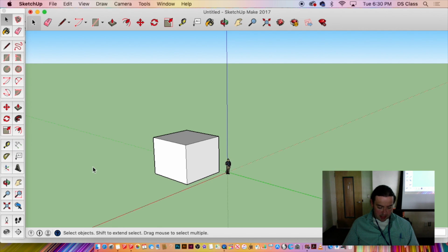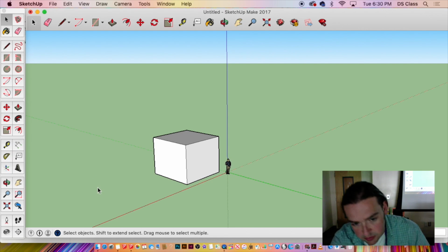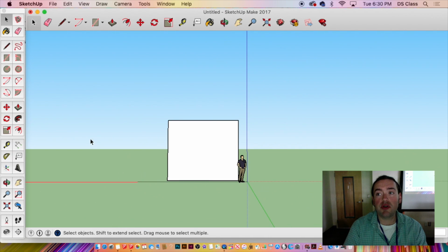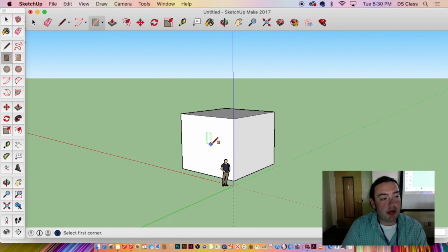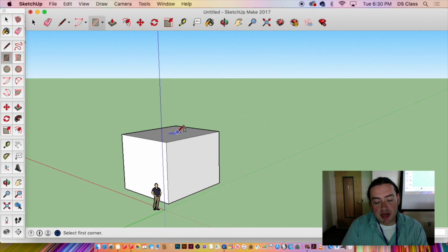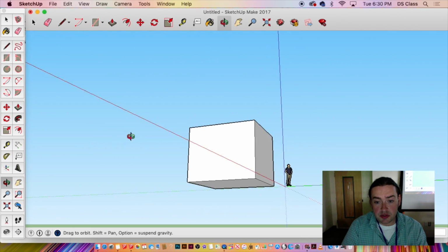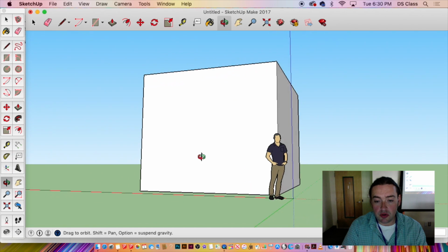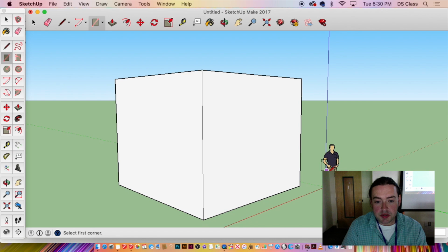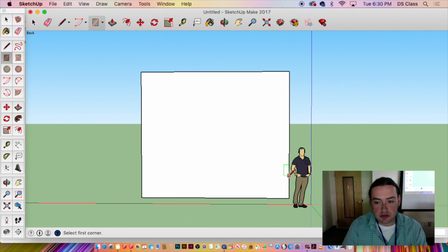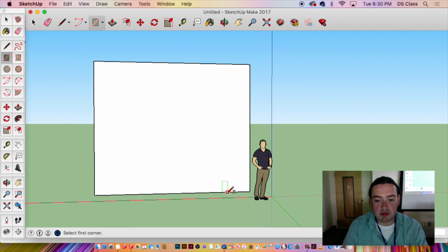So we got navigation in. Now we're going to look at some additional tools that I think will really help you out when creating and drawing and constructing things in here. So we can go back to the rectangle tool for a moment. Remember how I said we had snaps going on? I want you to look at the color that it assumes when you put it on different faces of your cube. So that means it's aligned to that axis, which is handy, believe me.